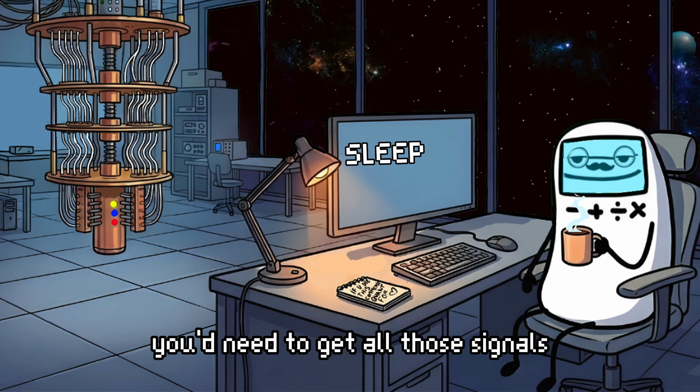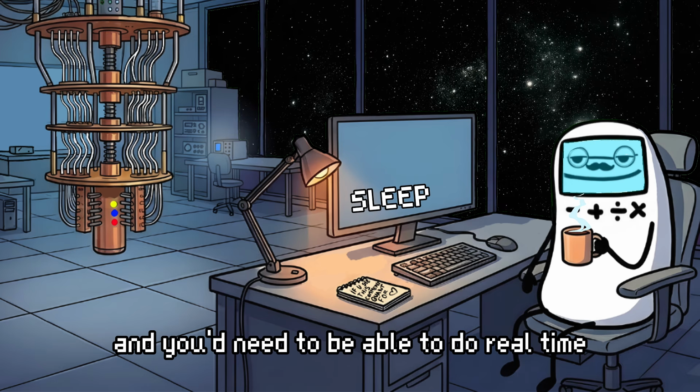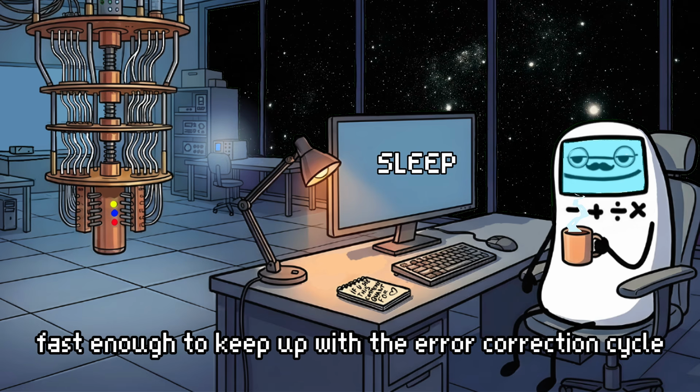You'd need readout resonators and control lines for all of them. You'd need to get all those signals in and out of the dilution refrigerator. And you'd need to be able to do real-time classical processing of the syndrome measurement results fast enough to keep up with the error correction cycle.